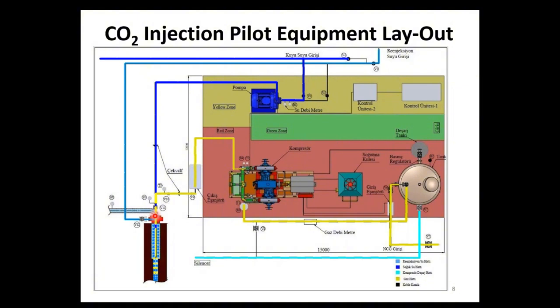The speed of moving down is not changing, but by volume it's mostly NCG, while by mass it is 80% water. After a certain time, the hydrostatic column of the water creates more pressure, and when it comes out of this parasite string here, there is NCG in a supercritical state.